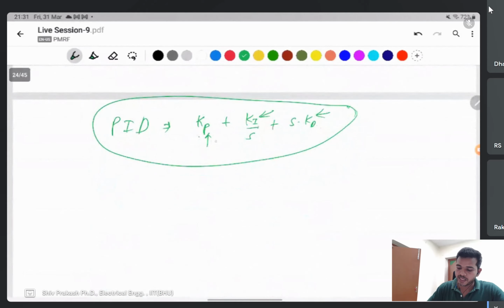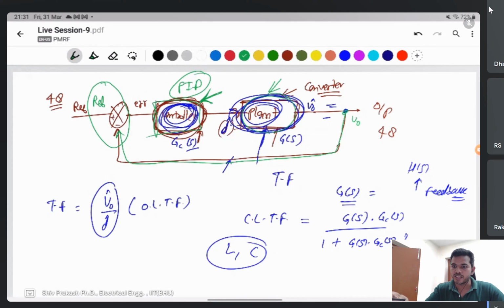But if you want to change this in the running condition, then this is called robust control. In that condition, you should track the input voltage, output voltage and inductor current. You sense both to give the feedback, with an inner loop and an outer loop, two loops. After that, you design a controller to control the whole thing. But here, for a normal controller, PID controller or compensator, you simply design by taking into account the plant transfer function only.